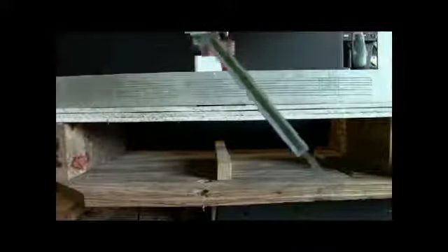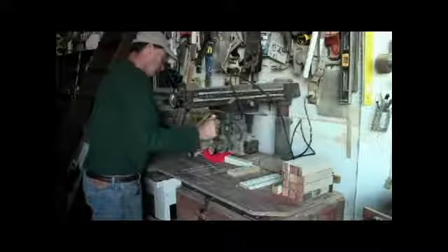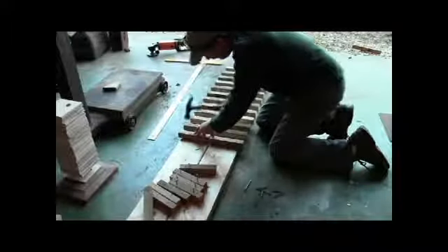The plank span is 19 inches, and the maximum allowable deflection is therefore 19 divided by 360, or 0.053 inches. So the minimum number of planks needed to meet deflection criteria would be 4 planks for that particular design load. I built a tall support structure so I could test the theory, hopefully confirming the PBS model.